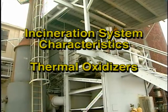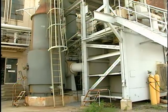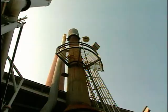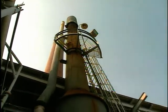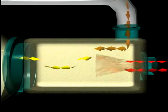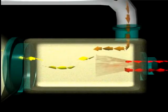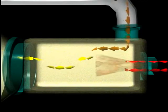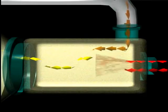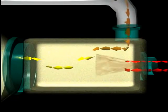Thermal oxidizers are used for contaminated gas streams that have an organic vapor concentration that is generally less than 50% of the lower explosive limit and usually less than 25%. The thermal oxidizer consists of a refractory brick-lined chamber that has one or more gas or oil-fired burners located at one end. The burners are used to heat the gas stream to the necessary temperature to oxidize the organic contaminants, typically 1,300 to 1,800 degrees Fahrenheit.